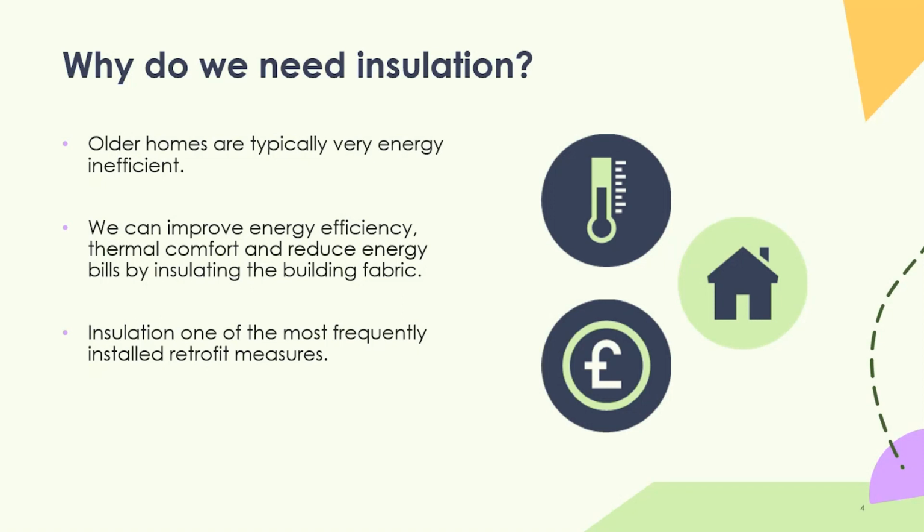So in terms of more modern homes than that, we typically still don't have an awful lot of provision for insulation. Cavity walls were really about trying to keep the outer skin of the wall with like a rain screen, keeping the inner skin of the wall dry, which did improve the thermal efficiency of the walls, but there was no provision for any kind of insulation within that cavity at the time when they were constructed. Certainly up to about the 1950s.